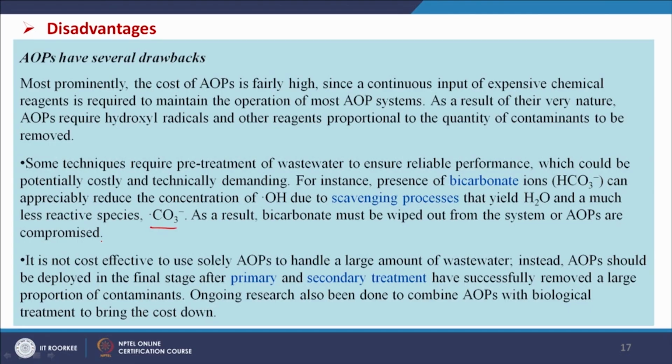It is not cost effective to use AOPs solely to handle a large amount of wastewater. Instead, AOPs should be deployed in the final stage, after primary and secondary treatment have successfully removed a large portion of contaminants. Ongoing research is also being done to combine AOPs with biological treatment to bring the cost down.